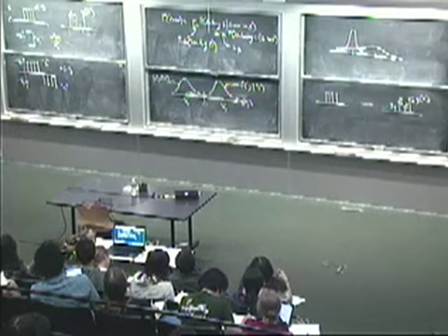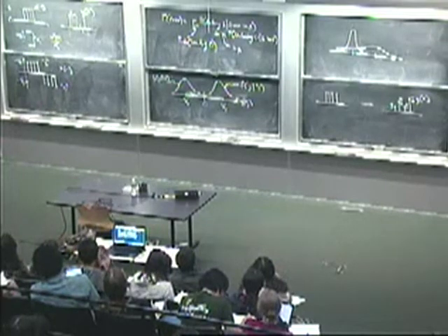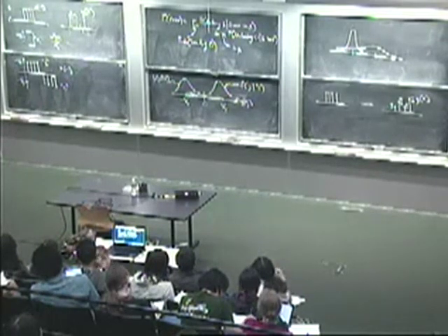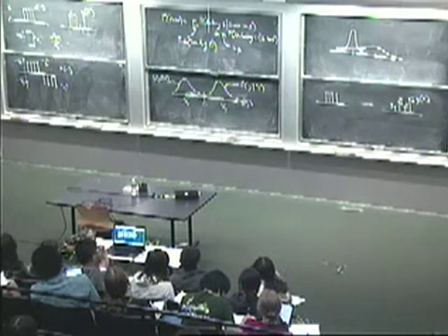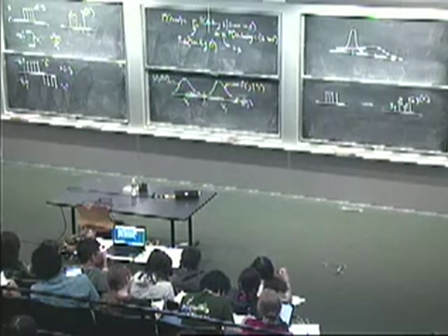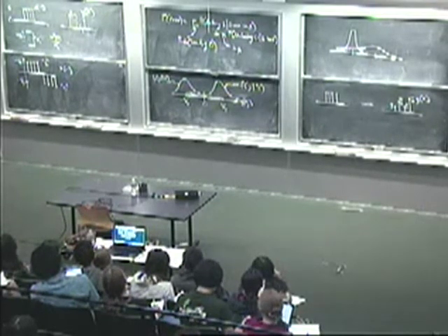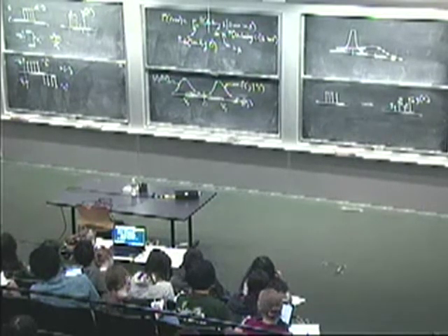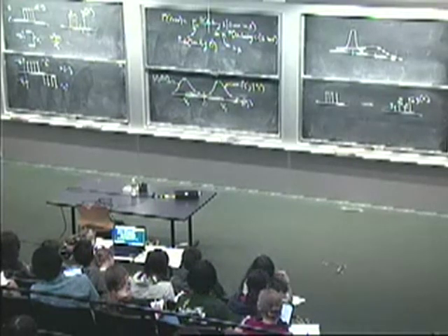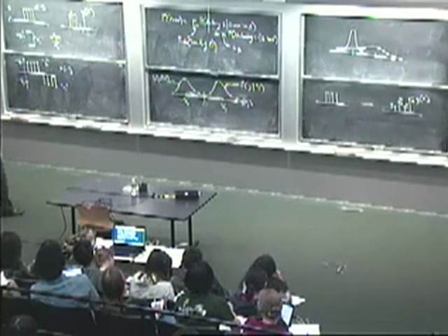So we're going to combine the received samples with some set of weights a n. Here's what it's going to do on the right-hand side of that equation. Again, when you take a weighted combination of zero mean Gaussians, you get a zero mean Gaussian. So all you need to know is what's the variance of a scaled Gaussian. So let's see.